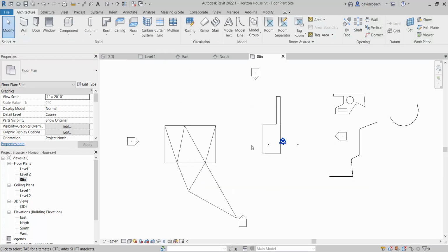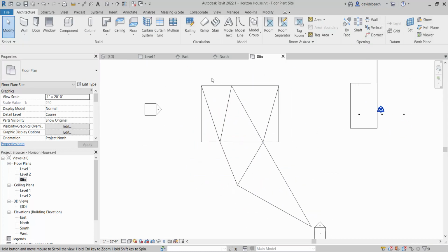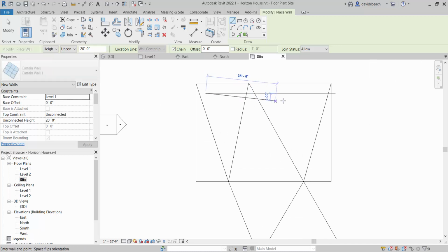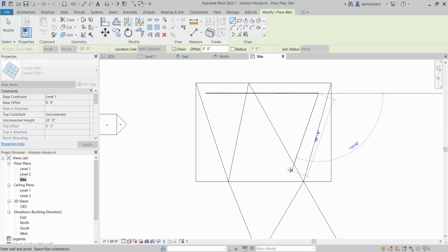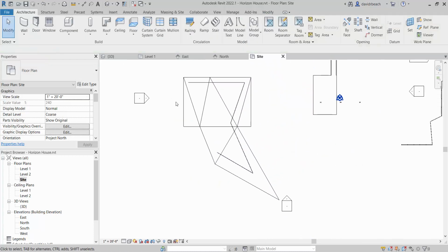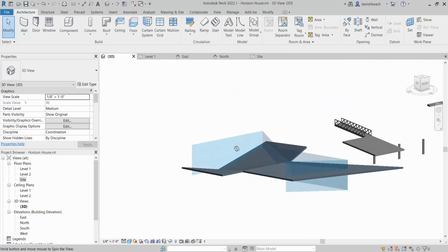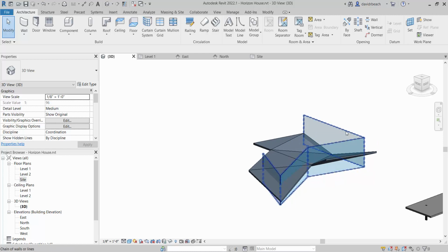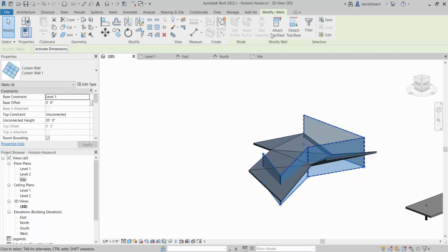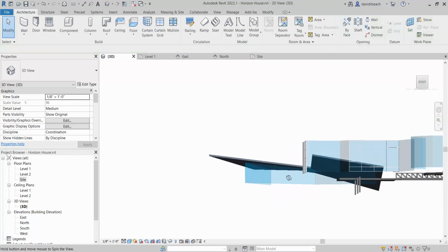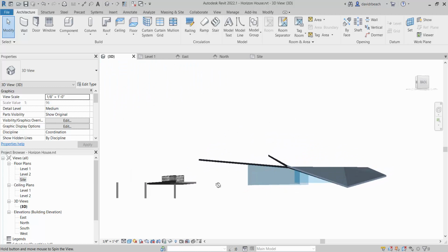If I am working with that and a set of walls, so if I had a set of walls that were running underneath this, yeah, let's just keep it on curtain wall 1. So I'm just going to do a wall, and here, and here, and here. Just as an idea, right? So that's what I've built right now. Okay? I can select all of those walls, and I can attach them to that roof, and I immediately go to that as well.